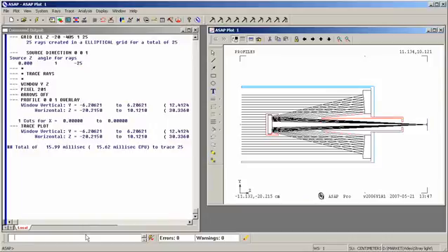We're then going to circle back. We're going to model the scatter properties in a more realistic way, showing how the BRDF fitting utility in ASAP can be used to model not just simple BRDFs like Lambertian BRDFs, but can also be used to model very realistic BRDFs, and this can be done in a relatively straightforward way, even by beginning users. We're then going to show how ASAP's importance sampling or directed scatter capabilities allow us to get the calculation done very quickly.